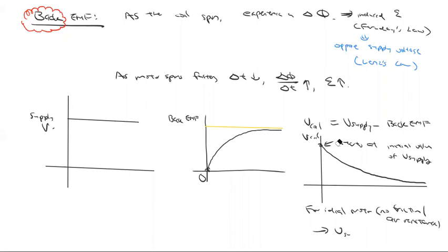In reality, it won't reach zero, because we need to put in work to overcome friction and air resistance. And most certainly once you start putting a load on, the motor has to do work. But that's the general idea. So your voltage is high at the start or whenever your motor slows down. That's why back EMF is often tested: why, when your motor slows down, does it break? Because your voltage is higher, so your current's higher, which means there's more heat. Why does it get hotter?